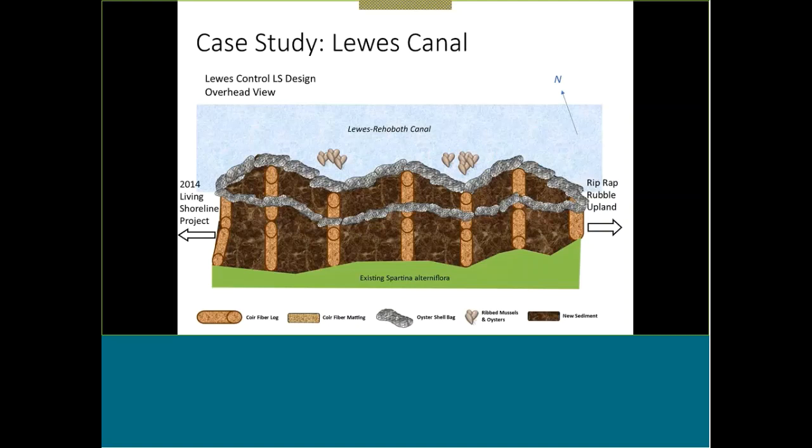Now, I'm sorry, I also wanted to mention that to encourage sediment accretion and give the project some stability, we wanted to install Coir Logs perpendicular to the project internally as well, kind of creating these smaller cells for the sediment to settle down in. This is our overhead view.